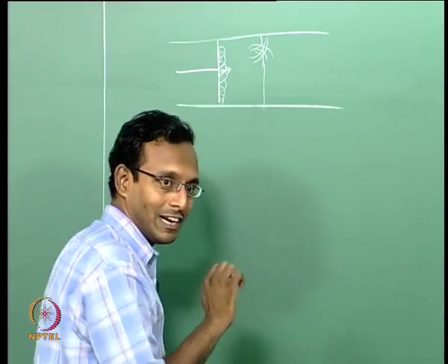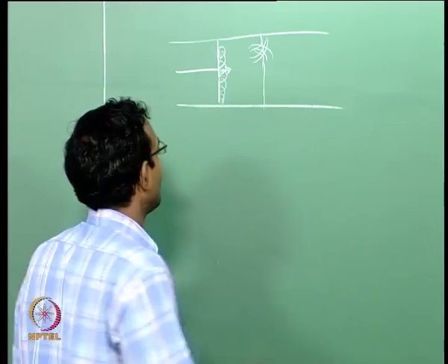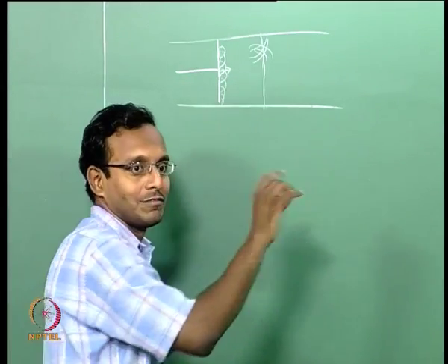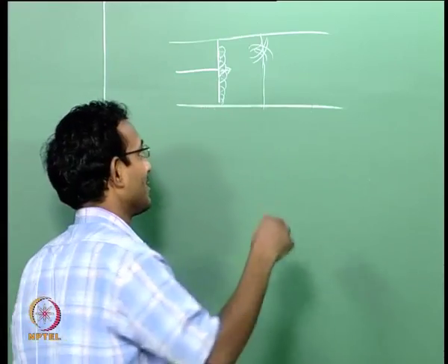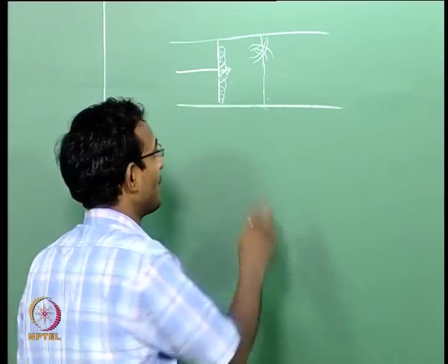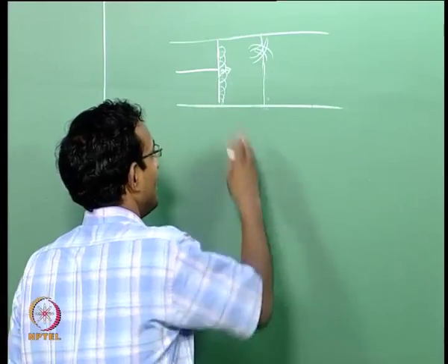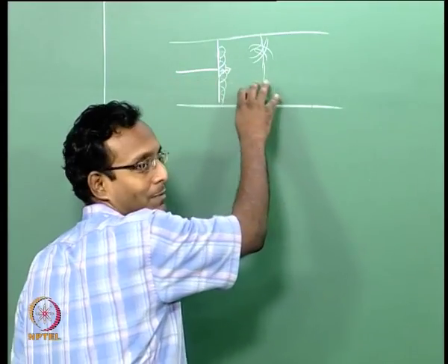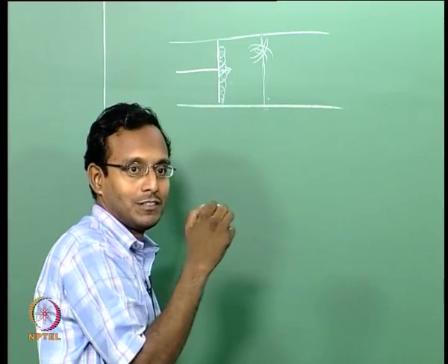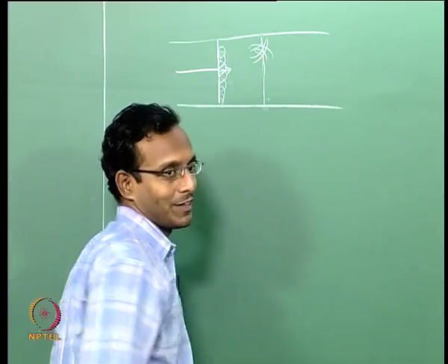If I move it a little more, if I accelerate the piston a little more, there are more compression waves created. What will happen if there is another compression wave created? That will go and reach the first compression wave. Why? We already discussed that. Okay. Previous was a compression wave, so the second wave will reach the first wave. Two compression waves together form a stronger compression wave. Okay. And if I accelerate the piston at a particular acceleration, it is going to go through with some particular shock strength. Okay. And that is how it just propagates.